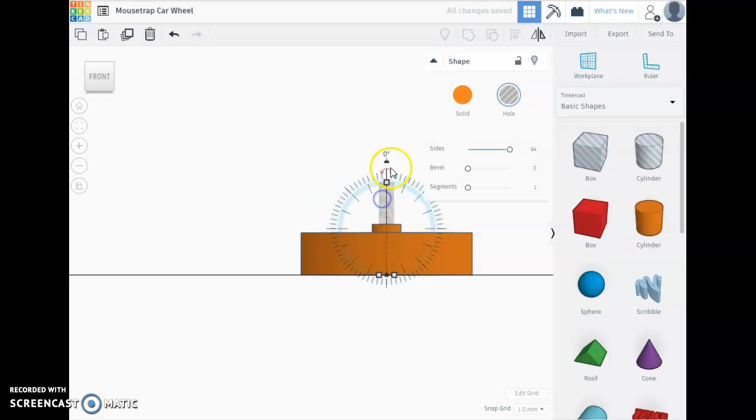Okay, I'm changing the height. I guess what I want to do is actually use this black arrow to move the entire piece. So I can move it up 5 millimeters. Okay, but I'm changing my mind. If there is no maximum, the minimum is here. The axle has to be able to protrude into the wheel at least 7 millimeters. That's the specification. But I'm going to make this so it can go in as far as desired, but given maybe just 1 or 2 millimeters of space to keep that from going all the way through the wheel. So I think we're good here.